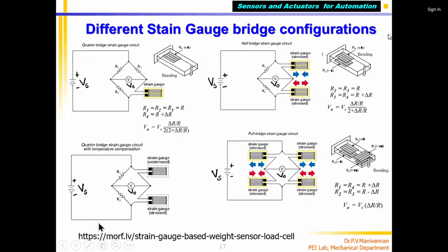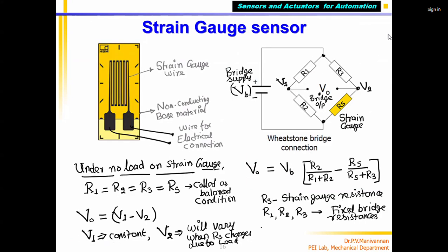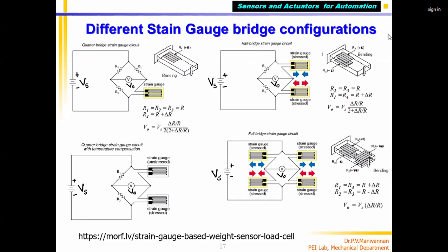Okay. Now, if you talk about strain gauges, they say strain gauge can be configured as a quarter bridge, half bridge, full bridge. Because we know that the Wheatstone bridge has 4 arms, correct? In the configuration, arm 1, arm 2, arm 3 are fixed resistance. I told you 120 ohms. Please note that this need not be 120 ohms. For example, this is 600 ohms, because I said 120 ohms strain gauge is there, 600 ohms, 1200 ohms resistors are there.